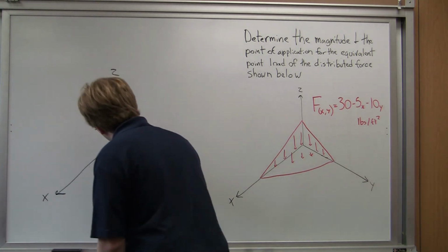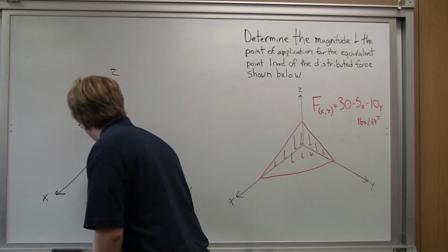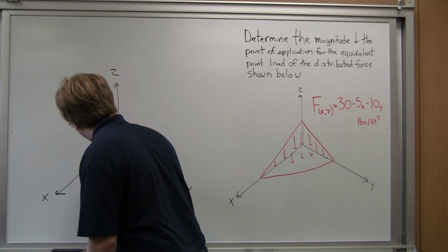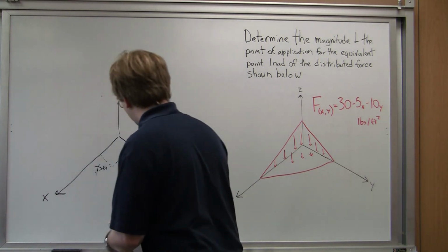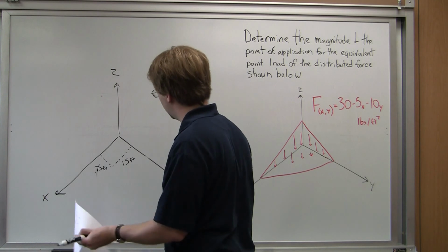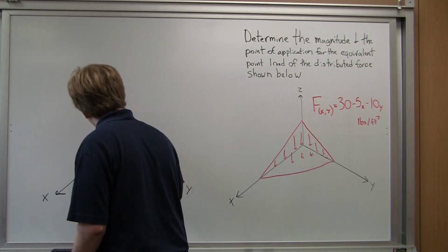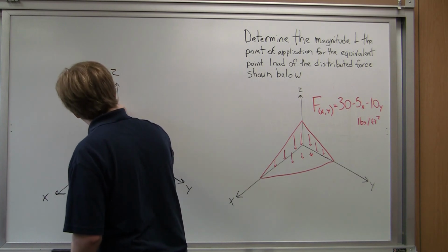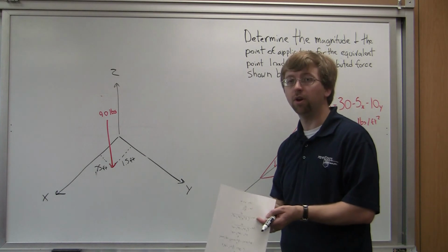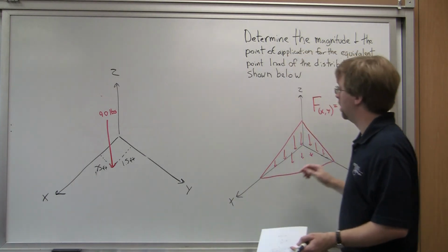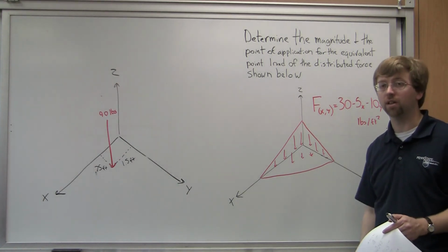So this is 1.5. This one over here is 0.75. And the magnitude of the force is 90 pounds. This single point load right here is going to be statically equivalent to the distributed load that I started with.